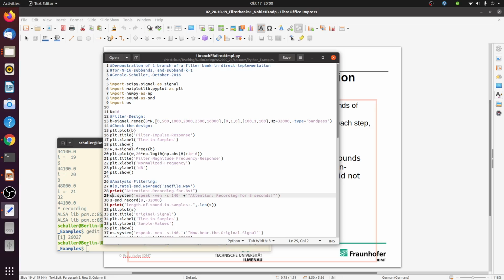In the first argument, you can see the number of coefficients it generates, in this case 8 times capital N, and here capital N is 16. So this is a fairly small filter bank with 16 subbands, and that means we also do a downsampling by 16. So not 1024, but just 16.